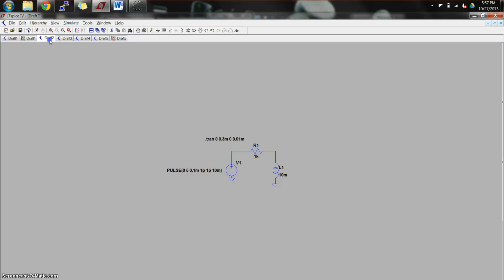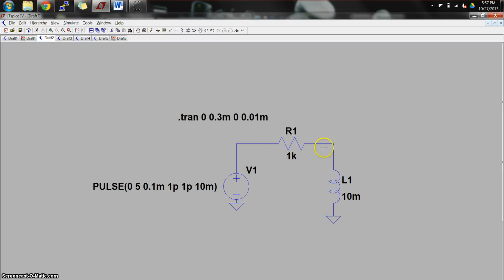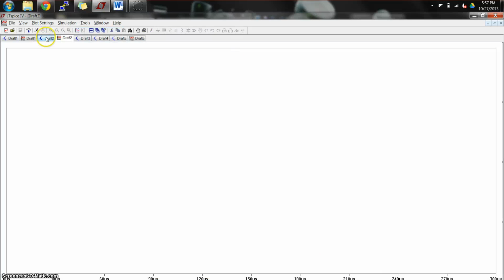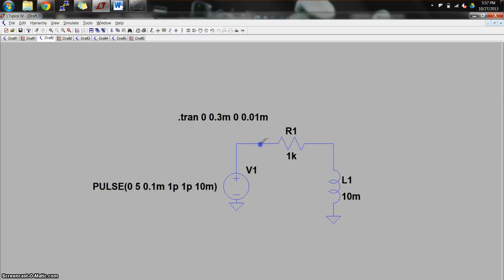And actually, while we're doing this, let's go ahead and do the same thing for an inductor circuit so we can see how that works. So the transient response of an inductor circuit, here's a circuit. I did a pulse function, so I'm going to be sending in a square wave, and I did a transient response. It's already set up, and you can look at my component values here. I'll click Run and bring up this data. I'll put the square wave by clicking right here, and I'll put the inductor voltage by clicking here.